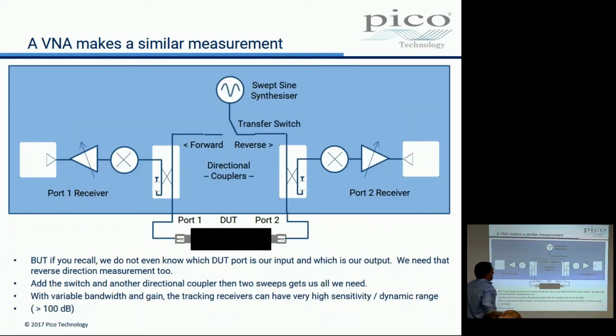What I'm now going to do is put a forward and reverse switch in the VNA, because what we want to do is measure the signals the other way as well, isn't it? So we can throw the switch over and measure that path through that directional coupler. Oops, where did that come from? Oh, I had to add that, didn't I? I had to add that because when I want to go this way, I've got to go through a directional coupler in there and out of there.